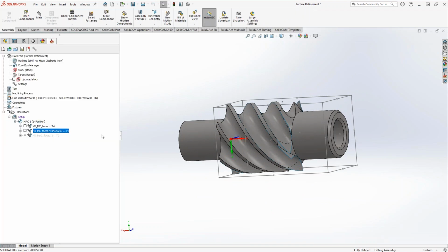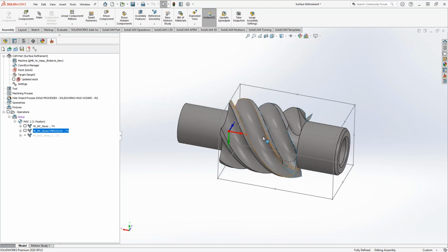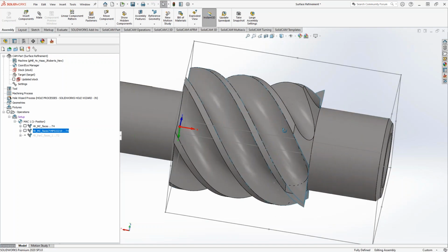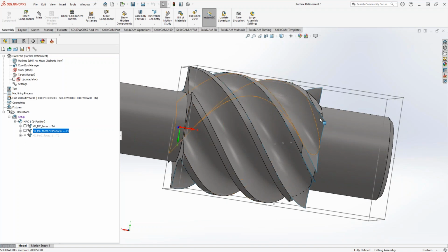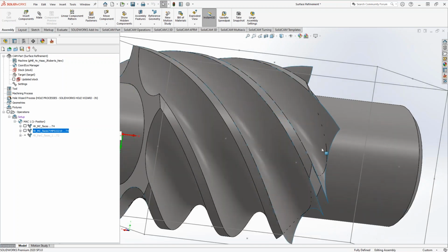So again, not that complex, on this part anyway, but this can be very helpful when you're doing a 5-axis part, especially like this one. When the customer showed me this part, they weren't sure exactly how to do their 5-axis, or in this case, 4th-axis toolpath. It can get really complex because if you're trying to do morph between boundary curves, or some sort of parallel to curve, and then you've got this oddly shaped trimmed surface, trimmed edge, you're doing a lot of retractions, you're doing a lot of trimming of the toolpath,